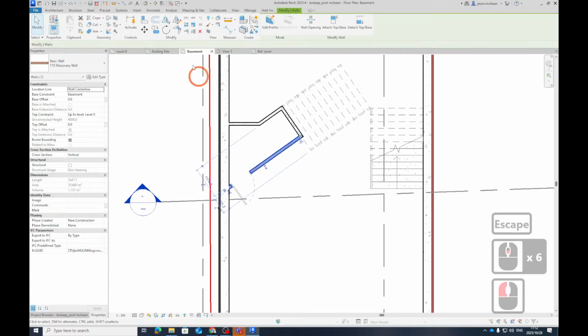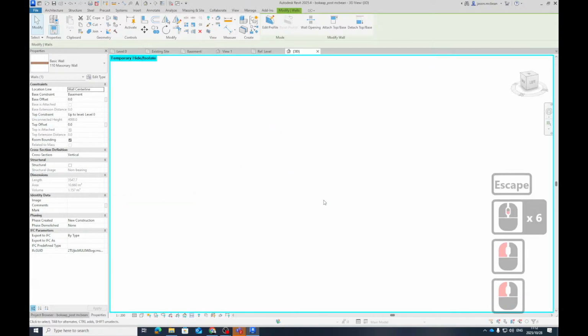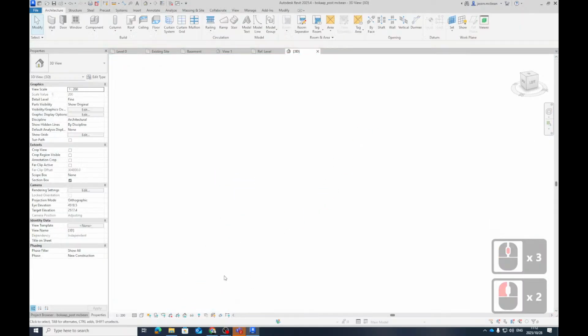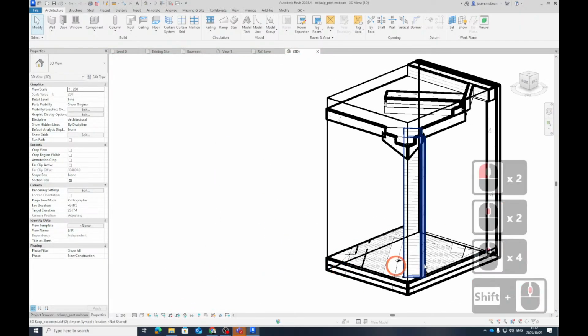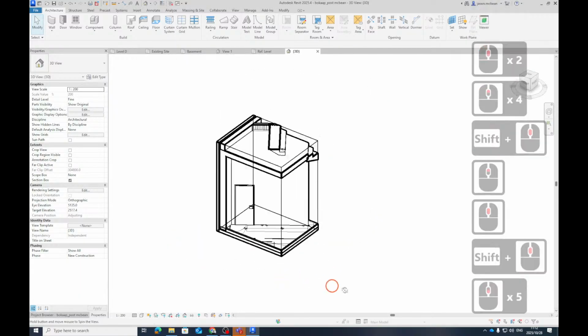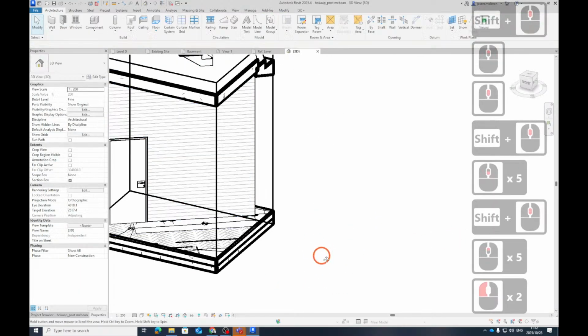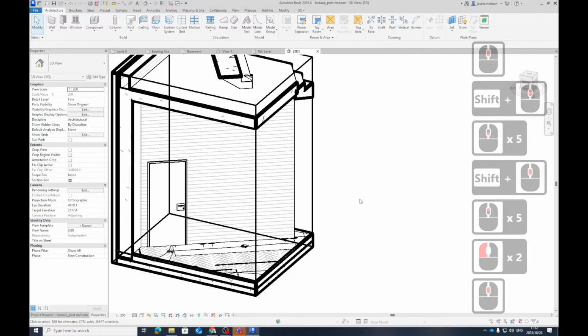can, let me just select this wall and go to 3D view. So I'm just isolating this wall in 3D, and reset temporary height, reset. I've just isolated that wall very quickly. What this allows me to do is model in place, I can model a door in place.